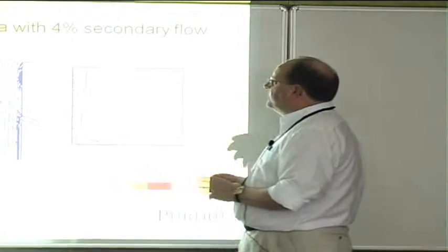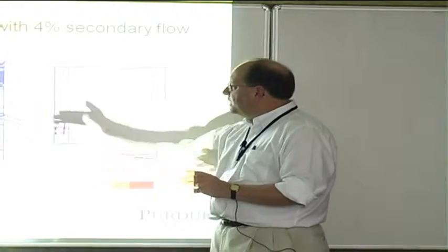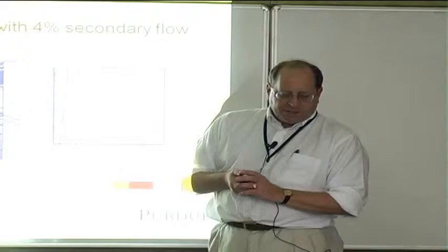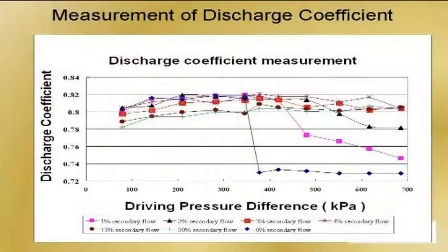And that ended up largely inconclusive, because we had a second style of injection slot we also ran, and the internal structures in those two flows, even though they both altered the droplet production, were vastly different in terms of the oscillation and whether the cavitation extends past the injection slot or oscillates up and down, and many other things going on. So that really turned out to be inconclusive initially.